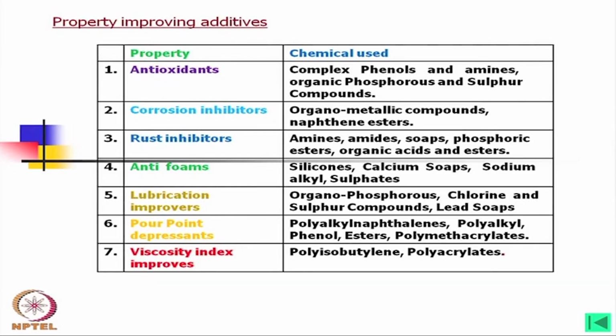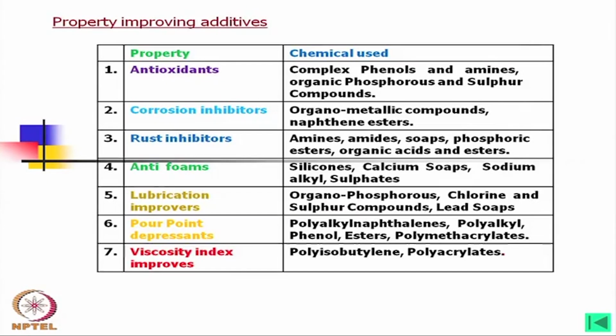You will find that when any water or any liquid is being discharged from a pump-like machine, when it is put into, say, a bucket or anywhere, foam will be there. Now, as such that foam may not be that harmful, but with that foam the air bubbles go inside the oil and that creates a problem. So, it is better there should not be much foam. This can be controlled from the outside also using, say, baffles and separators inside the tank, but these chemical compounds will help in a better way.